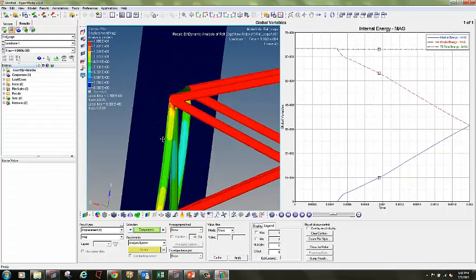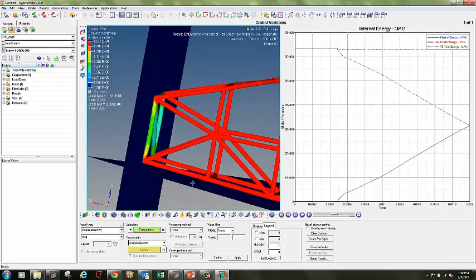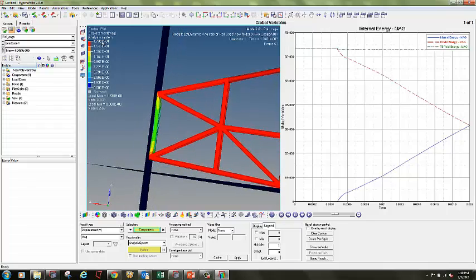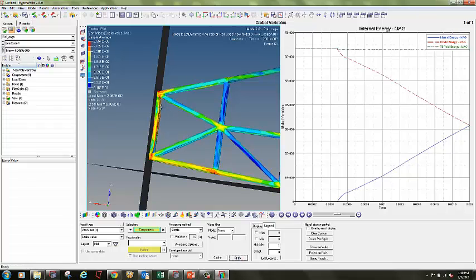So here the impact happened. You can see the displacement is continuously increasing as time goes on. I will see von Mises stresses also. So these are my von Mises stresses. Here it should cross these 2 points and then go back. Because of the lesser time frequency, the bouncing back effect is not captured properly. So I have to capture that bouncing back effect.